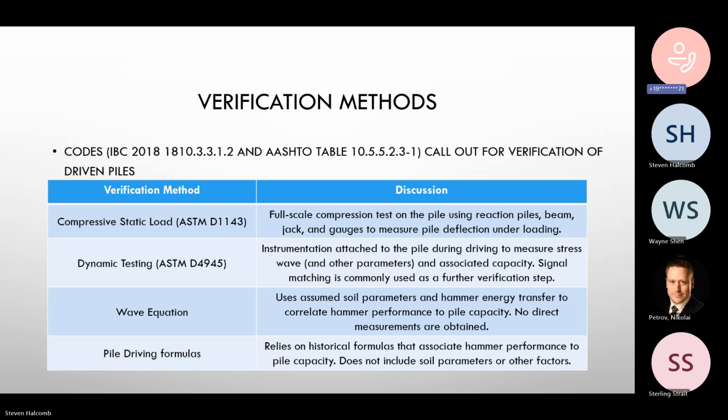So, the one thing to note here is when you're talking about capacity, a lot of times when I talk to structural engineers, there's this idea that the capacity is one actual number, and we kind of make it that way. We talk about it that way, but we could probably talk for an hour about what the capacity of a pile really is, because like any material, it has its own modulus. The soil-pile system has its own modulus, and it's only pushing back depending on what kind of soils and materials are there.